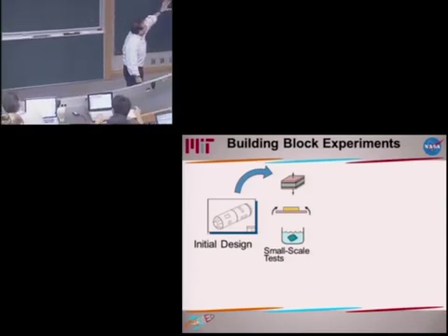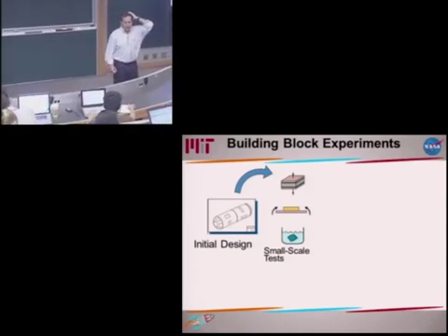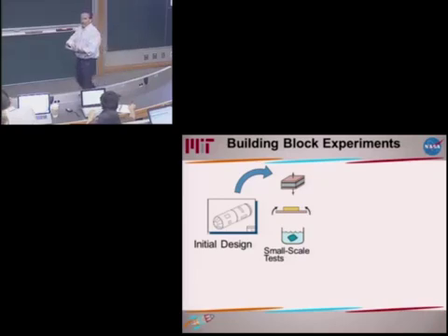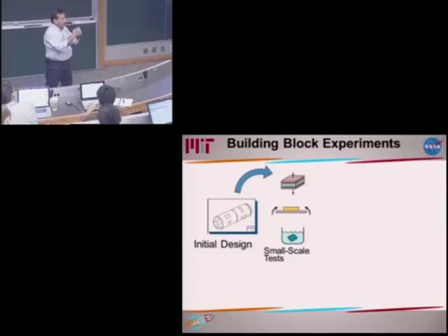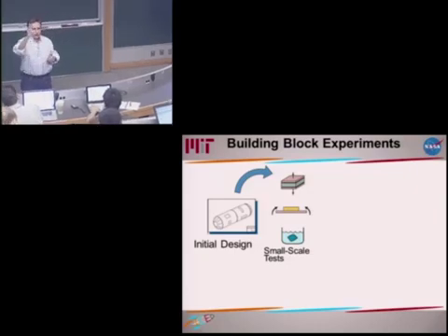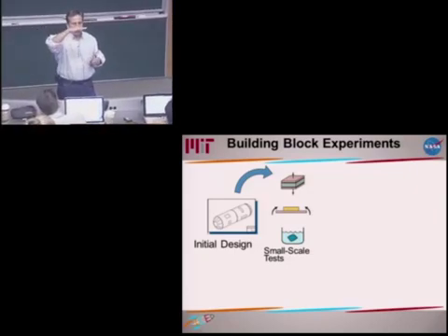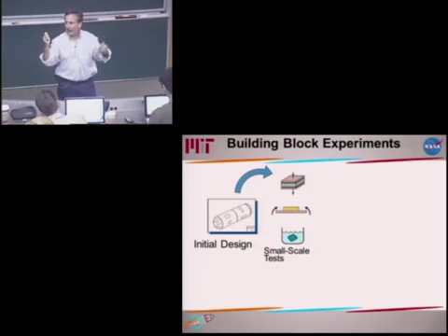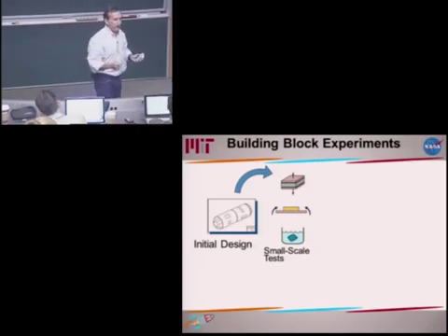So what I said was, you know what? If this is going to work, you have to maintain that vacuum. If you don't maintain that vacuum, if it leaks, if you get hydrogen going into that sandwich panel, or if you get air going into that sandwich panel, it's so cold it liquefies. It liquefies, and then once you launch and the tank boils down and the sandwich gets heated, it can't vent, and that's going to blow up that sandwich panel.